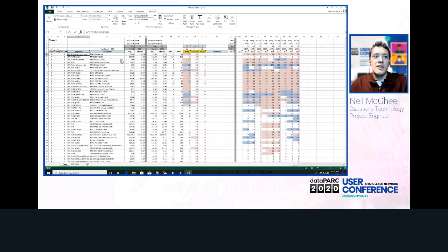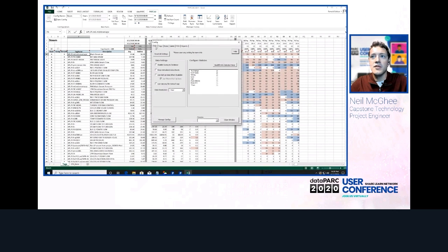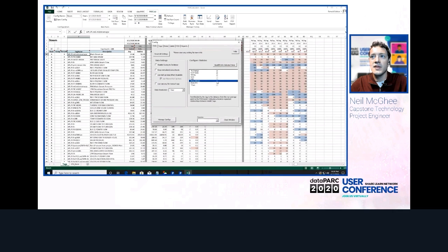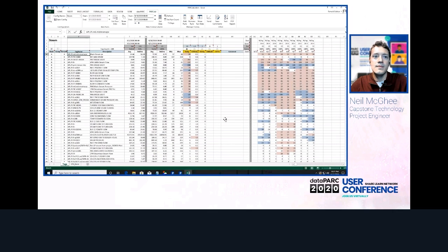And then we want to go into the configuration menu. And under the data tab, we enable those last two statistics based on the PCA model. And finally, we want to recalculate the statistics for one of our comparison periods. Before we look at the PCA statistics on the deviation detection tool, I want to give you some insight on what each of these statistics means.